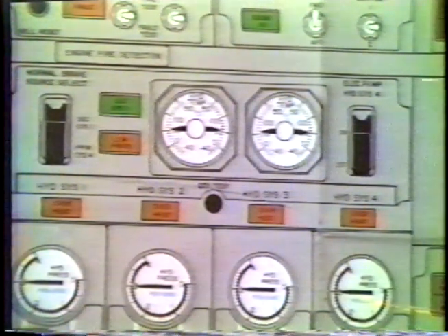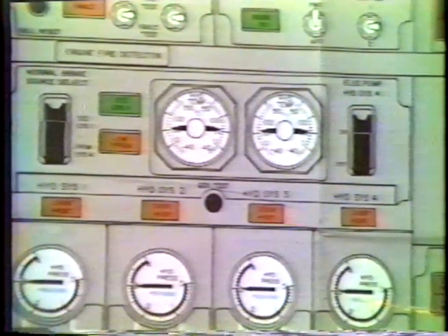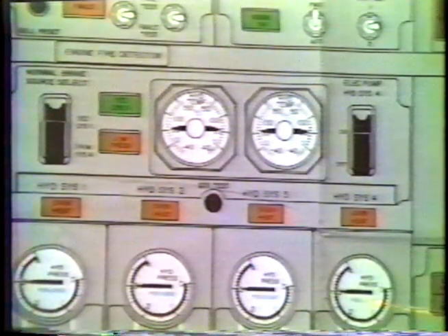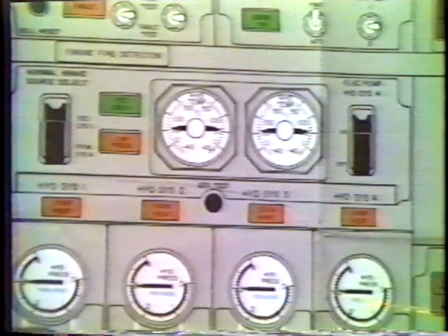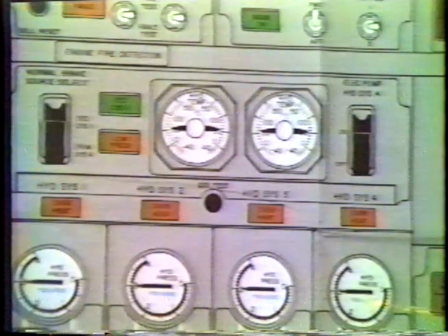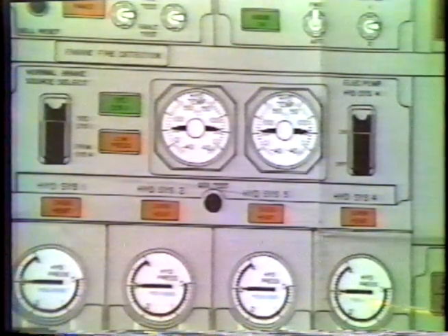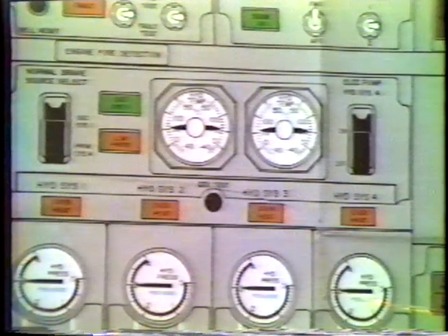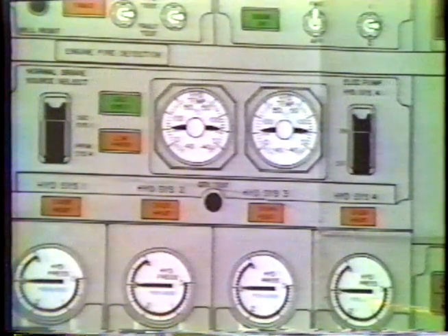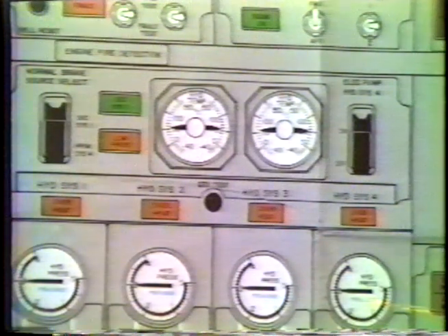Now, also, if there was excessive fluid dynamic flow throughout the entire system, it would cause the temperature to go higher than normal. Not that there was excessive temperature at the pump, but the entire reservoir, the system, all its lines and everything heat up. And then adding the case drain temperature to it would cause this to go to a higher than normal temperature.